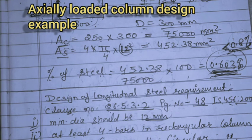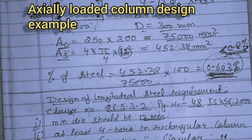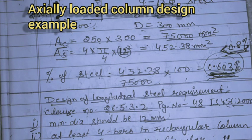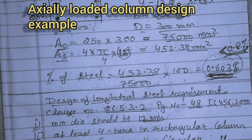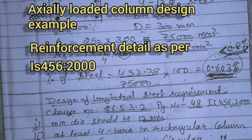So in the last class we discussed compression member design as per the limit state method and some codal provisions and assumptions as per IS 456:2000. We calculated the maximum load carrying capacity of the column in the last video. Here we are going to take some design examples of columns.